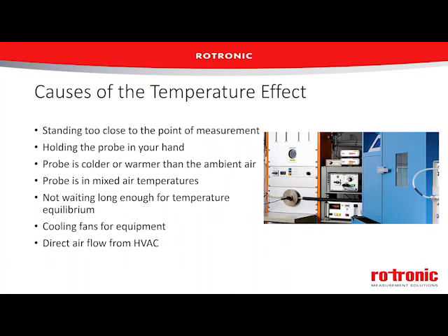We also need to be aware of any equipment in our environment or other sources that could create local hot spots or cold spots. Cooling fans from computers or other equipment are a very common issue that we need to deal with. We need to make sure we're not measuring in the direct output of that hot air. Otherwise, our relative humidity will read too low. Same goes if we're in the direct airflow from an HVAC system. Those are usually blowing cold air into our room. And so if we're in that direct airflow, we're going to be measuring a relative humidity that's higher than the average throughout the room.